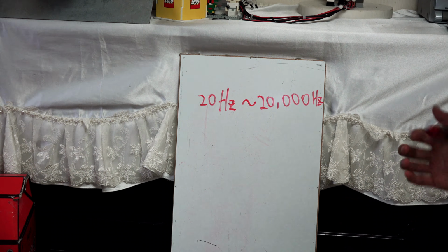I put trig as 8, and I put echo pin on 9, so I write this. And I began in this setup. I began my serial to use serial monitor, and I use pinMode trigger for output, and pinMode echo for input.